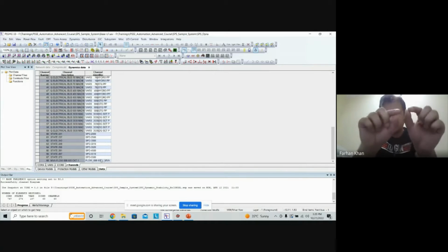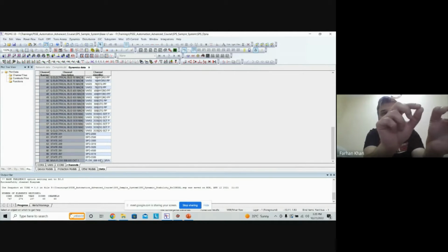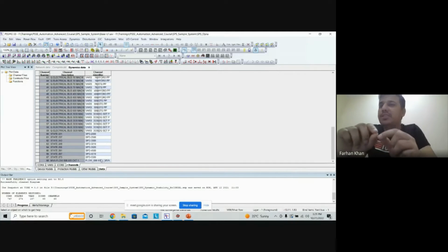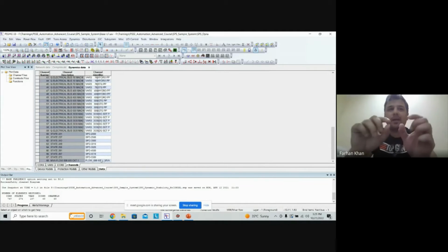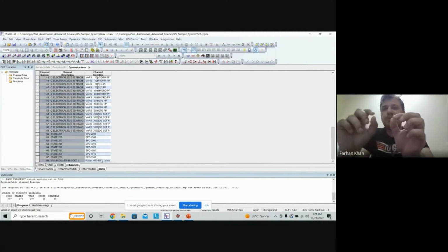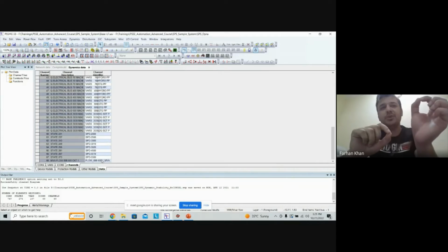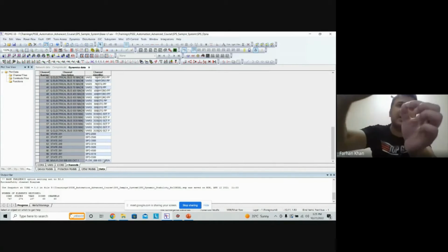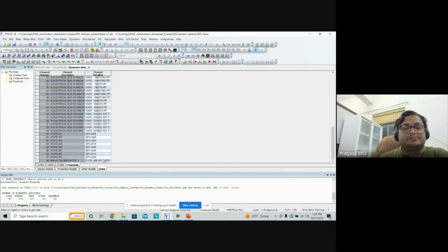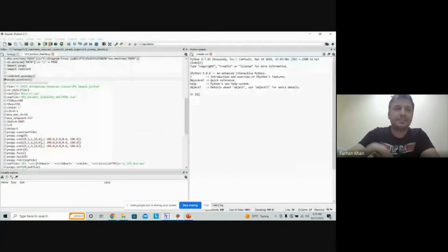So for this particular case, channel number 68 is the point of interest for me. Similarly, in your case, you are going to monitor the frequency. So from frequency, you are going to calculate the rate of change of frequency. So again, your point of interest is going to be the frequency channel, whatever channel you want to bring. So this is how it is.